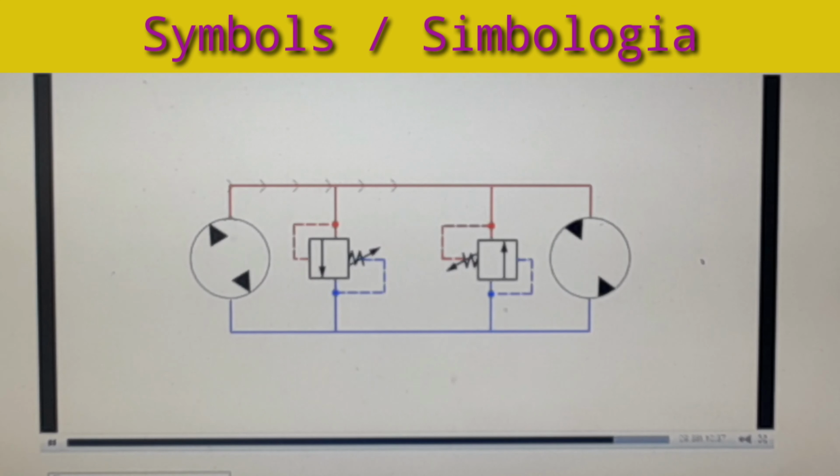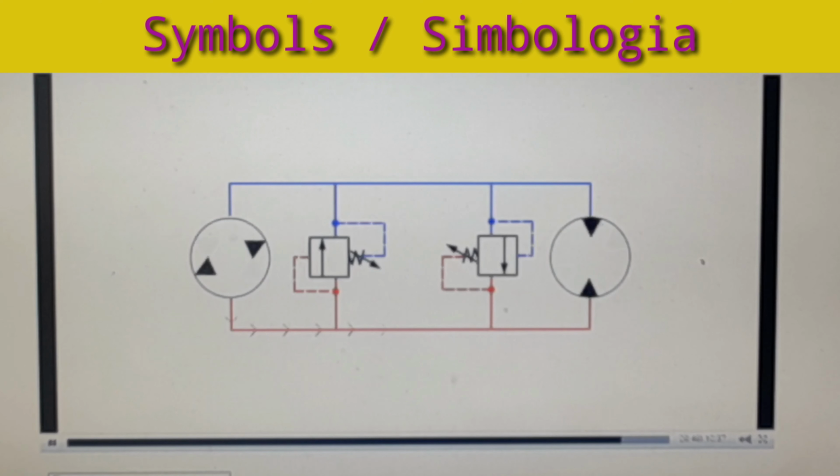The pump flow changes according to the operator's demand. If the circuit pressure exceeds the setting of the relief valve, the fluid relieves back to the low-pressure side of the closed-loop system. The control valves in a closed-loop system do not return fluid to the reservoir.